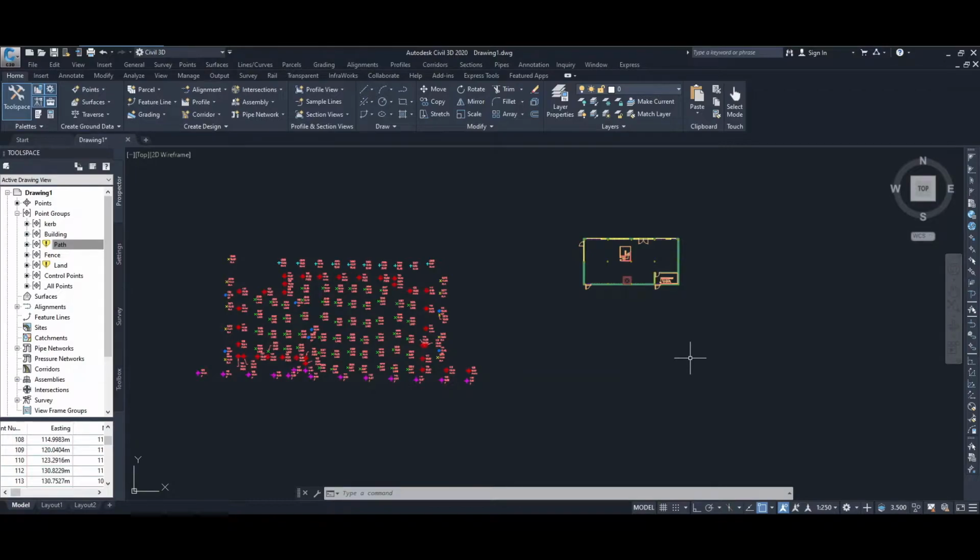What we'll need to do is to position this drawing onto our site with the points that we have created. Our own local grid isn't purely horizontal. So what we'll need to do is to take our drawing, turn it around slightly so that it's orientated onto our site, and then place it within the green area.